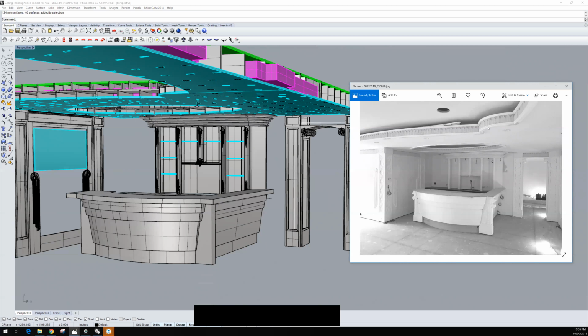And then we pulled down one piece at a time, fastened it to the ceiling up into this plywood, fastened one piece, clamped it up, and then worked our way around both top and bottom. And then after we got the top and bottom molding put in, we applied the J.P.Weaver molding across there. You can see there's some J.P.Weaver here above our panel sections, this crown molding in the top here.